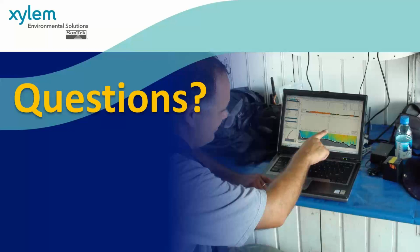Yeah, and if I could just add one thing, the network RTK is a great option, but some of the same restrictions, guidelines and assumptions apply as using a base station on the bank of the river with you. You need to have a virtual connection to an actual base station via the network RTK that's close enough to provide accurate corrections. So if you're in an area that doesn't have nearby network RTK stations, then it might not be an option as well. So thank you, Xue. That was a good question.